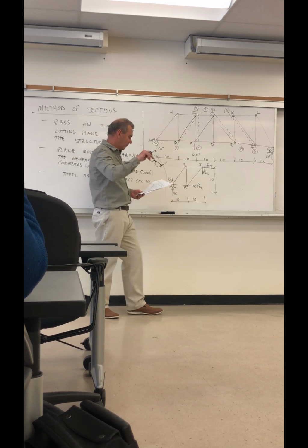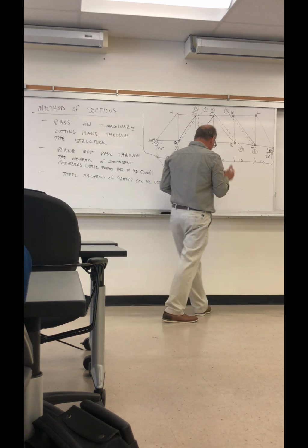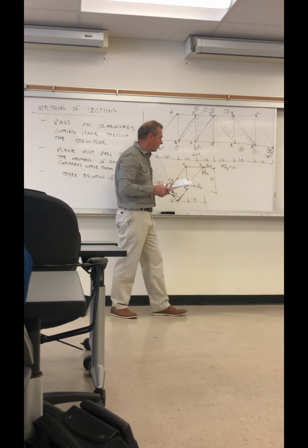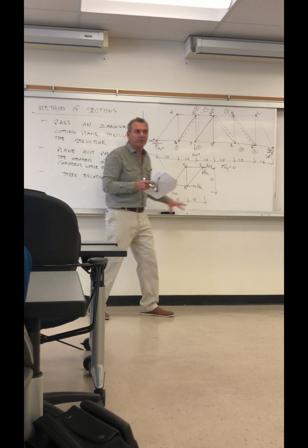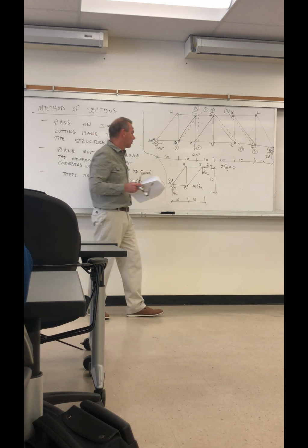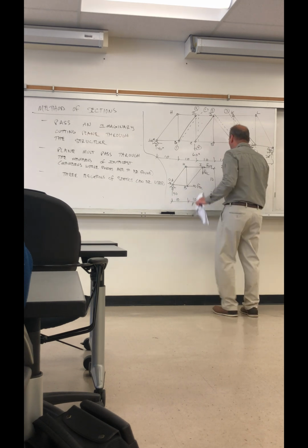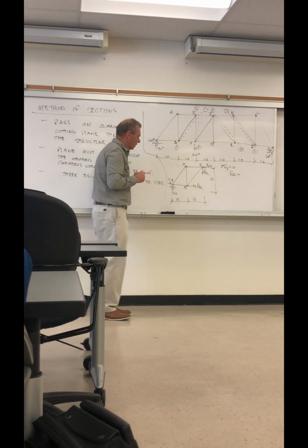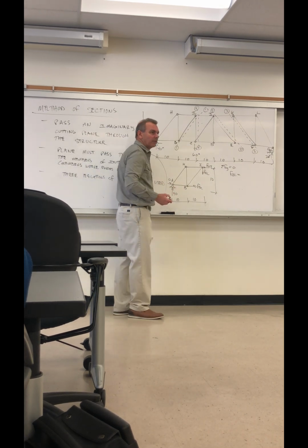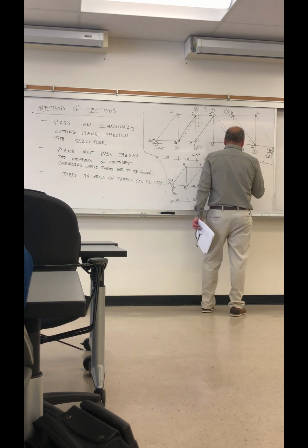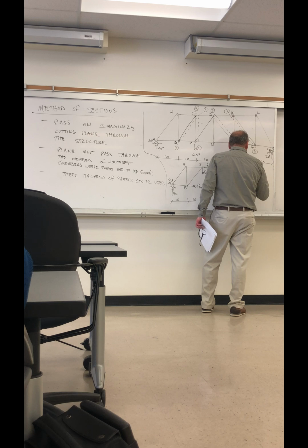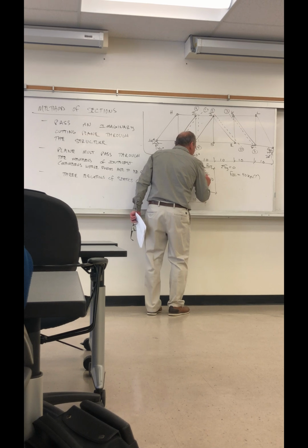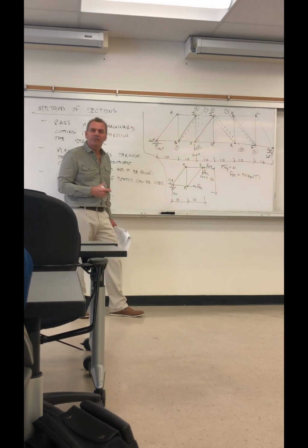Okay? So now this is interesting. Let's do this first. Summation of forces in y is 0. So we're not just summing these forces at a section, we're summing for this whole picture, okay? Statics as a whole. So we can see right away, look at this. What's F of IC equal? It's got to be 40, right? Summing forces first, it's 40 kips, and it's in tension. That was it. That's a simple calculation, right?